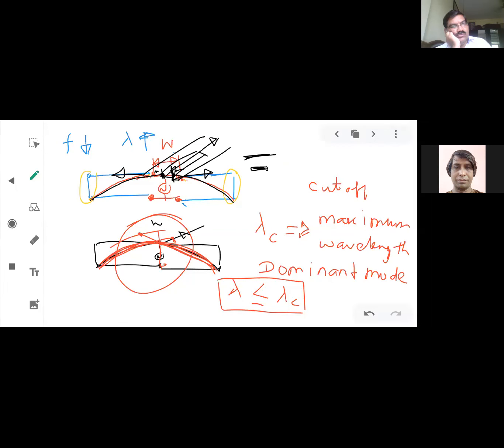And here finally it was concluded that the moment the two quarter cycles merge to form a single half cycle, the effective width of the central strip vanishes, and there is a possibility that the delivery of power from the generator to the load is going to fail. So that is the limiting case. This is the maximum wavelength for which the delivery of power can be made from the generator side to the load end. And that's why this waveguide is called a high pass filter. A waveguide is a closed structure, or a single conductor system, and it behaves like a high pass filter.